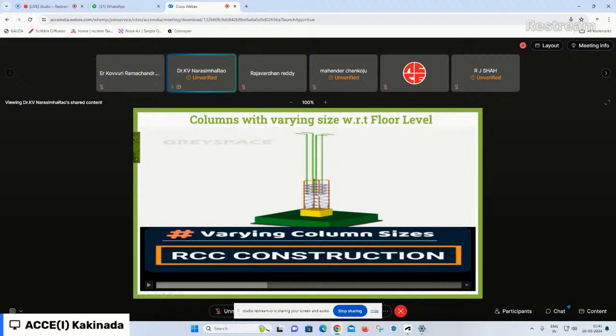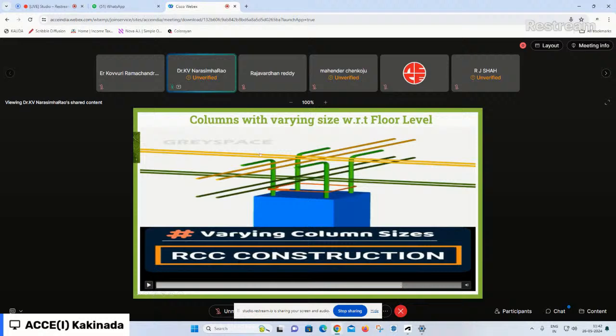So it should start from the bottom of the beam and extend up to a distance of LD, enclosed by closely spaced stirrups at a pitch of not more than 150 mm. These bars will extend to the topmost column of the reduced size, and at the ends, where it is flushing with the beams and there is no further continuation of the column, there should be a bending of these bars. That is, this bar length should be equal to LD.